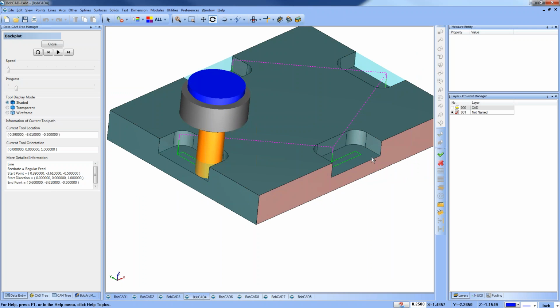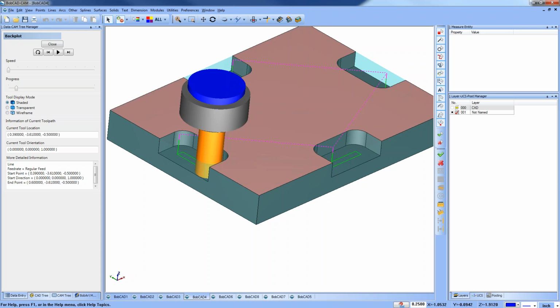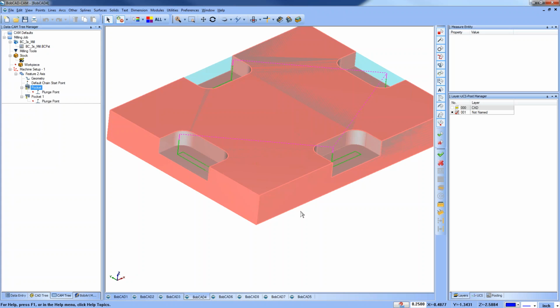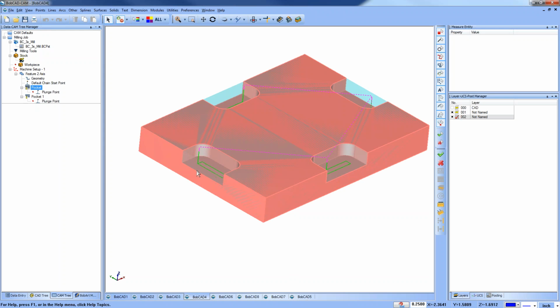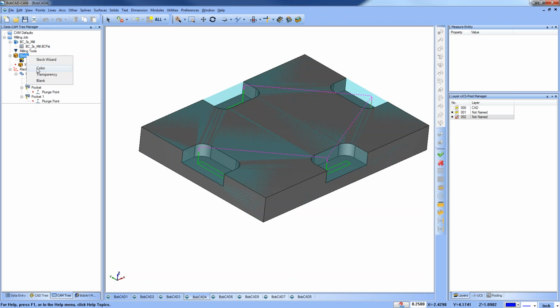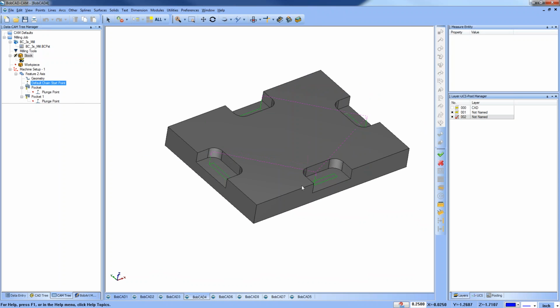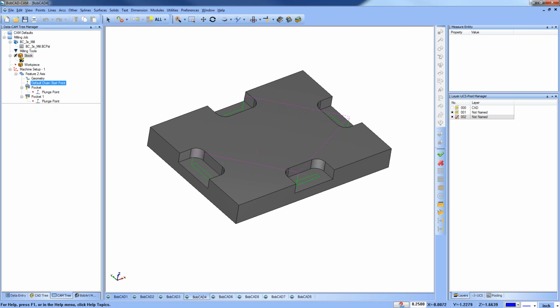But again, so we want to come in from the outside, but by selecting just this face, we're not able to come in from the outside. So what are we going to do there? We're going to have to change our boundary. So this is where we would create wireframe. And the reason why we're going to create wireframe is because we use a certain type of wireframe in order to set our boundary for an open pocket, or what we call an advanced pocket.